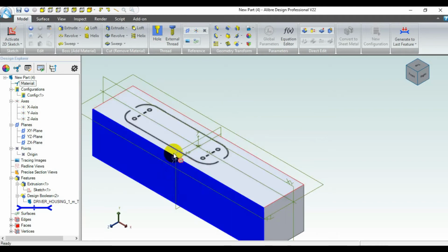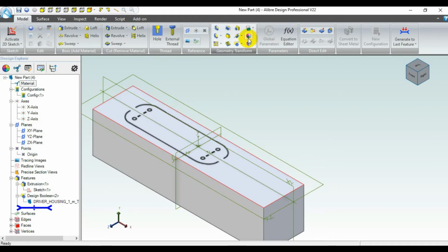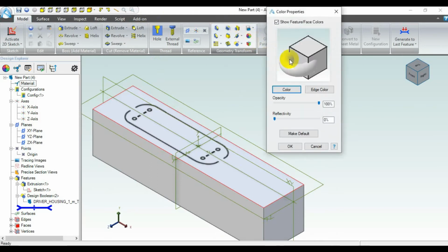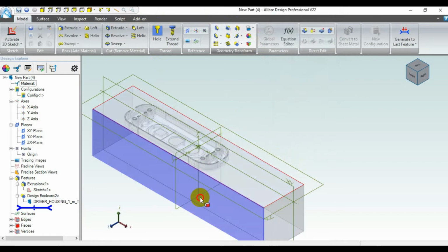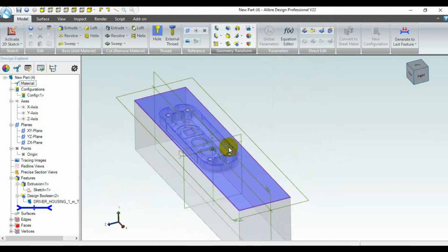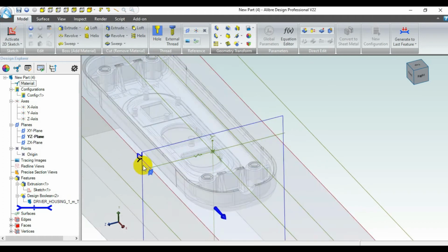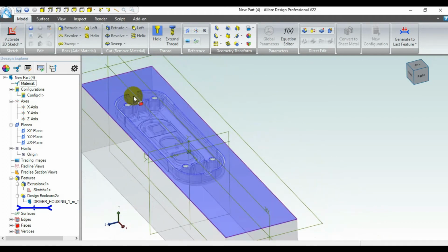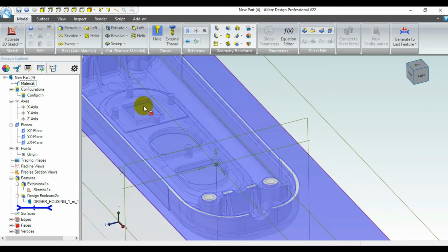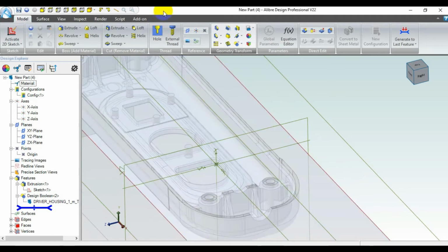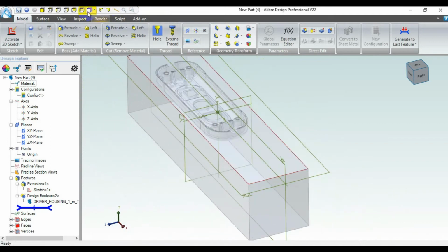Now at the moment with our part, I'll just demonstrate what's wrong with it and how we can't just use it as is. I'll make this a little bit more translucent, and you can see what's going on below the surface here. There is our part immersed in here, and it's subtracted from this block here, so it's basically the equivalent of fresh air. But at the moment it's attached by this tunnel through here, and also by these buttonholes for this particular part here, making it all one component. So if I try and subtract a separate component here, it's not going to work.